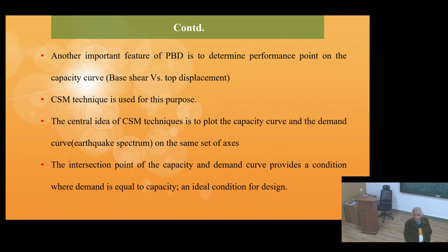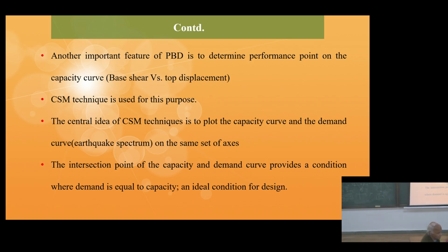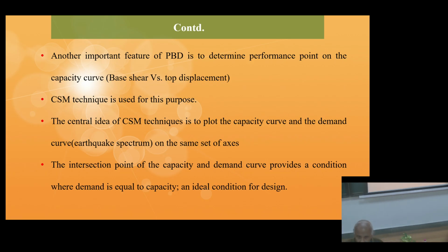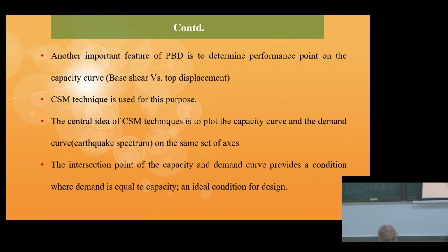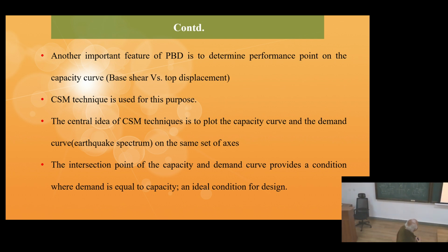And as I was explaining in the beginning, that is the SASD plot. In the SASD plot, I have to put both the capacity curve and the demand curve. And the intersection of that basically is the performance point, where we say that capacity is equal to demand.